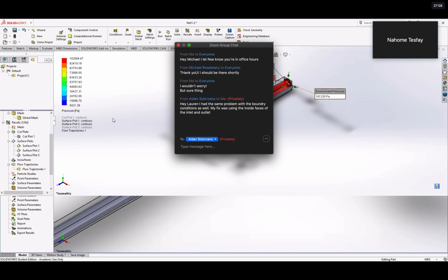Yeah, Michael, something to consider is that if the fluid's slowing down, then you can think of it as a force pushing it back, right? So the pressure is increasing because the fluid's slowing down. If the pressure decreased more, then the fluid would be going even faster at the outlet. So I think you're fine, right? Because you have the pressure increase at the exit. I mean, it's just atmospheric pressure, though. So it's the same pressure that the entire flow would be experiencing, no? No, the inlet has a lower pressure because the fluid's moving quickly. It has less space to move through, pretty much.